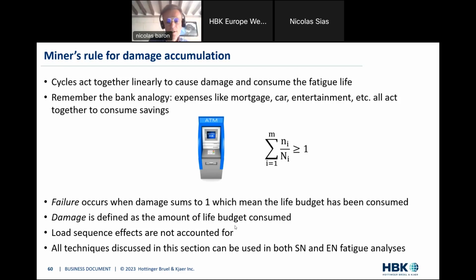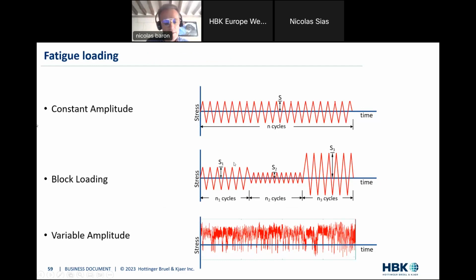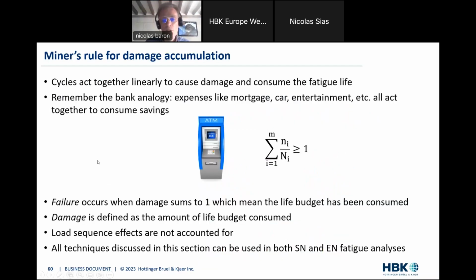Each of these cycles, the ones we see here, will fatigue your component. They will induce some fatigue mechanism within your component. So here we've applied them for a given number of cycles, and what we will do here is calculate the amount of fatigue these small n1 cycles have generated within our component. And how do we do this? Well, we look at the S-N curve, and we know that this component can withstand this capital N number of cycles before failure.